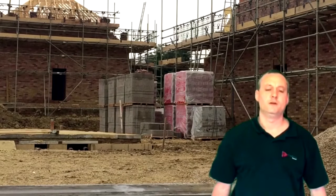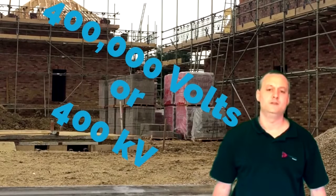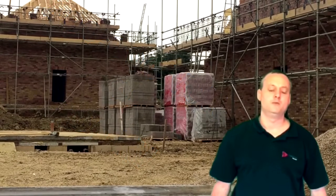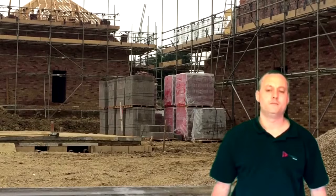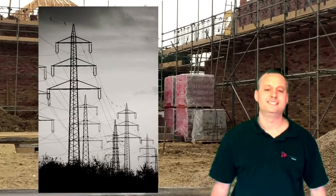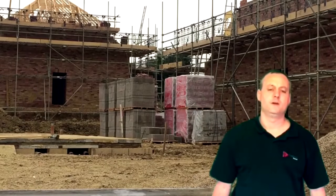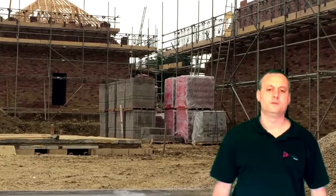So in other words, we've got a maximum voltage in the UK of 400,000 volts or 400 kV being used on the supergrid, super high voltage, but therefore we've brought the current dramatically down, making the conductors on the supply authority side considerably smaller. We did go on and mention some of the losses in transformers, even though our calculations had perfect transformers with no losses.